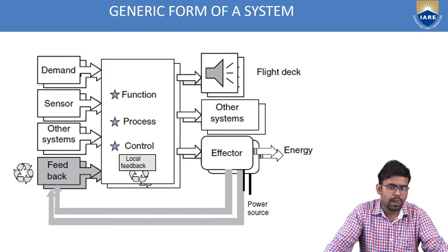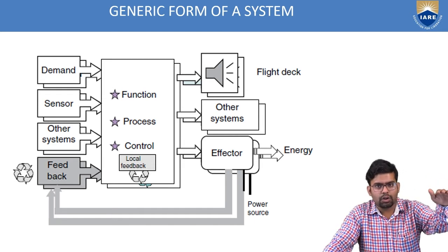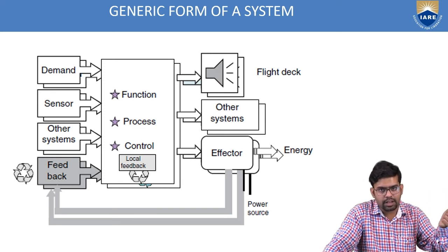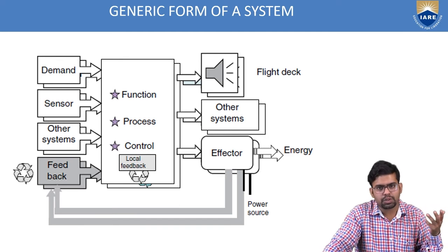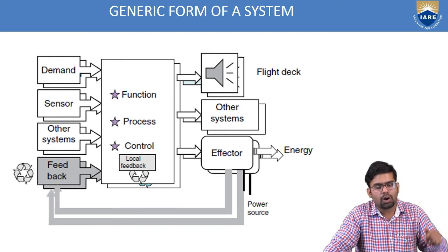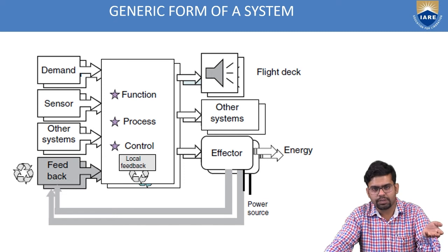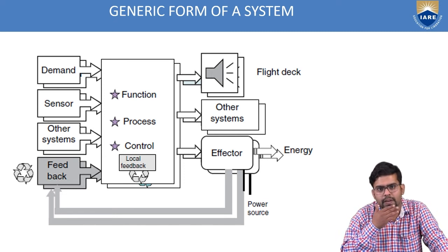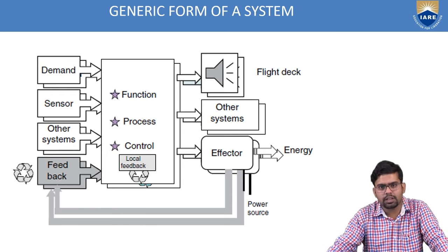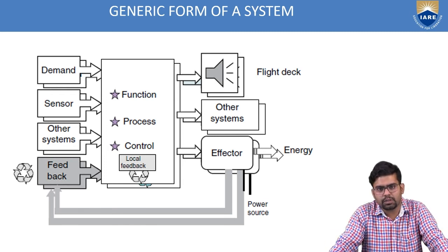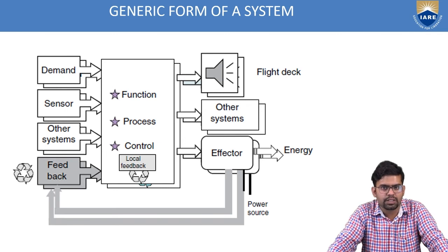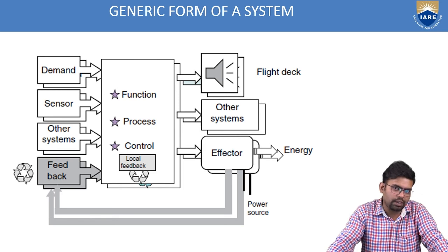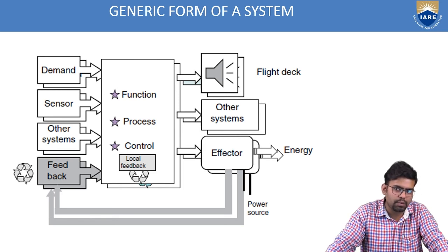So what happened was, all of a sudden there was stall. Stall is nothing but loss of lift. Once the aircraft is stalled, you overcome stall either by pitching down or giving extra thrust. But in this case, that was not possible. So 2 aircrafts crashed in a period of 6 months. The first one was Lion Air, an Indonesian-based airline, and the second one was Ethiopian Airlines from Africa.